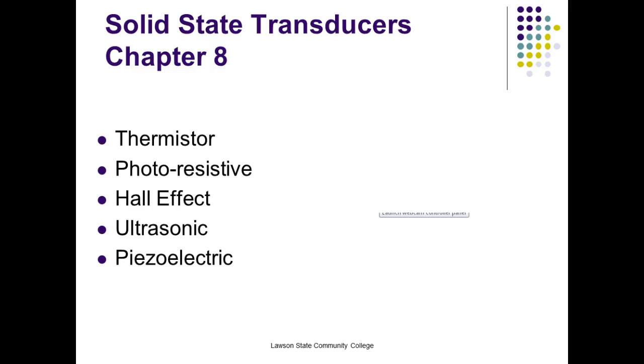Thermistor, thermal resistor, thermistor. So what does this guy do? It varies its resistance, but you don't touch it. I mean, it varies its resistance with what? With heat. That's what it does. Thermistor. I mean, that guy right there is just about in the name. It tells you what it does. So you can see what they've done is just shorten it down, but it's a thermal resistor. And of course, they shortened that down years ago to what we call a thermistor. And we have two types. We have what we call an NTC and a PTC.